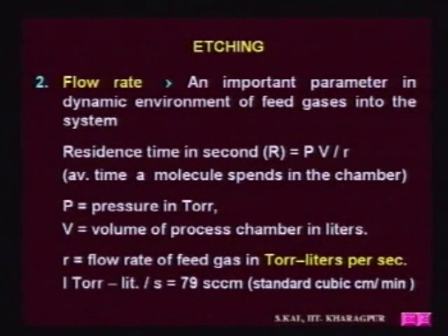Next is the flow rate, because when you are creating plasma, you are introducing some gases, and that gas may be argon or maybe freon, maybe oxygen, maybe hydrogen, etc. The flow rate is an important parameter in the dynamic environment of feed gases into the system. The flow rate gives you a residence time, that means how long the gas molecules will stay inside the plasma